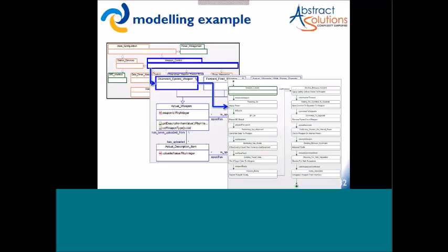So we might have had a requirement that said a wing-carried weapon cannot be ejected when the aircraft is flying upside down, because then there's a severe risk to the aircraft. And as we build the model of the precise behavior that works that out and controls that, questions will occur to us such as, well, what happens if the aircraft is rolling at the time and there is a chance that between starting the eject sequence and completing it, the aircraft will become upside down. So that will raise a question, and that will, as Jeremy described, feed back in and inform the requirements at that level in the system. And we'll have to clarify those requirements with subject matter experts to understand them.